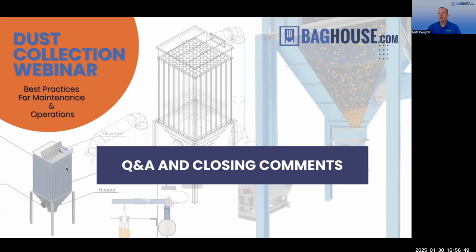Well, we have a dust collector maintenance checklist, which we've given out to a bunch of different people. And whenever I do these kinds of things, I always like to deliver that checklist as just a template, because every system's a little different. But the things on that checklist are pretty much the same regardless of your system. It's checking your differential pressure, listening to your pulse valves, doing occasional filter inspections, stuff like that. Checking the operation of your fan, belts and sheaves. If you have a screw conveyor, checking your chain drive and stuff like that. There's probably 20 or 30 different items that you can add on there, and you could break them up between daily, weekly, monthly or quarterly.